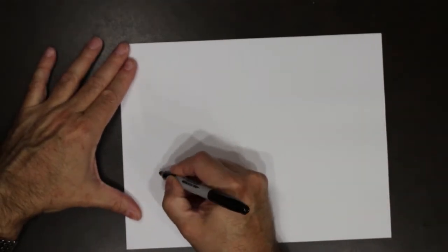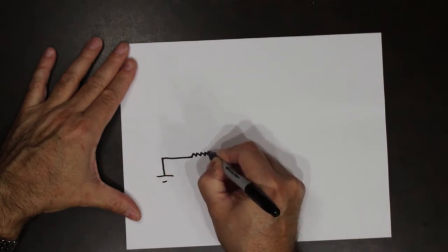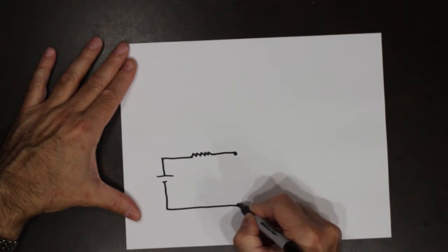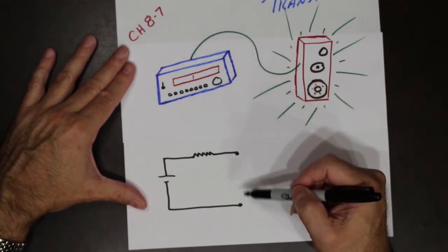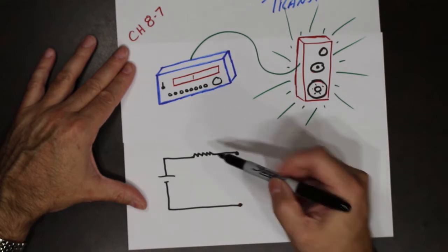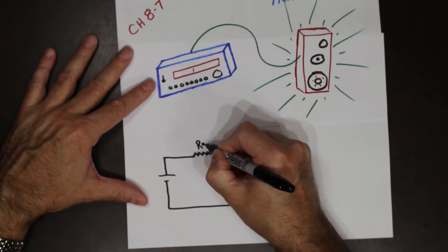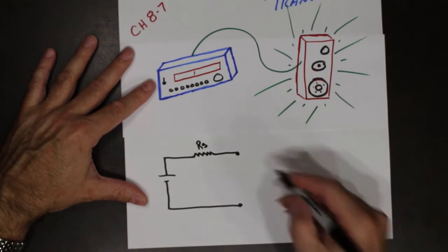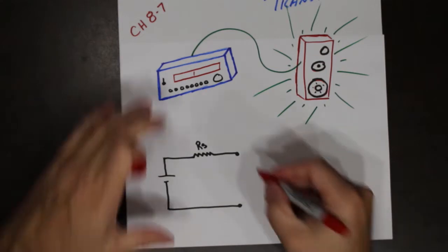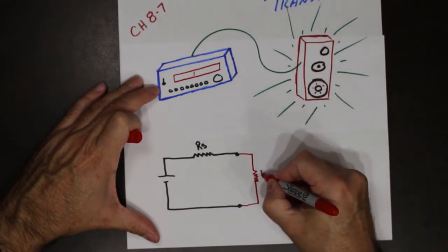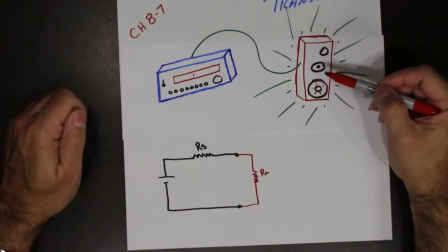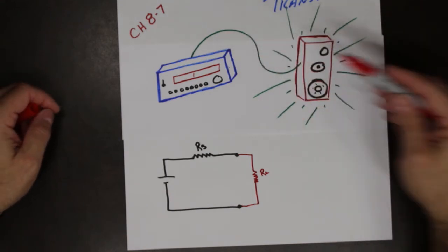So what we are going to do is look at a basic circuit. I'm going to really simplify it down, and we're going to go with black box theory. So our stereo translates into something very, very simple. It looks like this, where we have a power supply and some components that give us what's known as a source resistance, RS. Then we connect that to our load. In this case, the load is the speaker, RL.